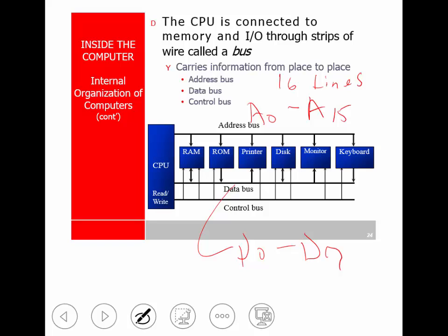When we talk about the control bus, it's actually a series of control lines, and they are not numbered the same. In other words, the control bus will have things such as address latch enable. We'll get into what that means. I already talked a little bit about the read write not line. It may have another line for synchronization. These are 4 or 5 lines that control the flow of communications. There may be an I/O/memory not line. So are we talking to memory, or are we talking to an input-output device? So this is the way that this is connected.